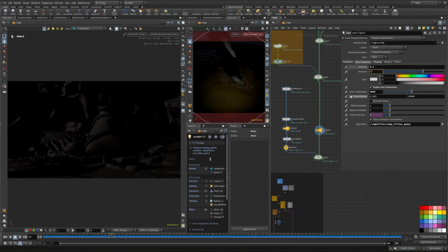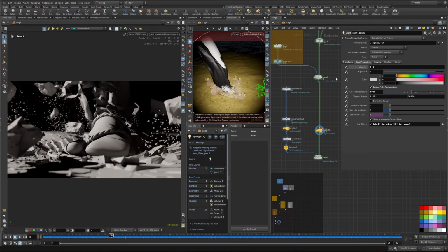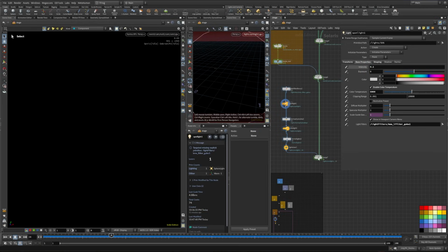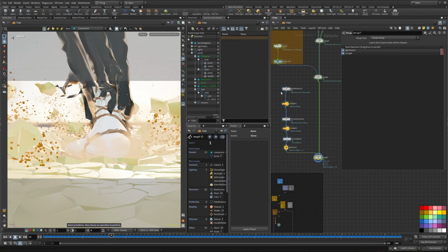Let's also increase the exposure for the view here, so we're using a value of 7. And let's move it a little bit more up. So maybe I'm using something like this here. Great. Now let's move it back to 0, plug the spotlight inside here again, and let's watch the end result. And yeah, that's looking pretty good. So we can disable the scene view here.